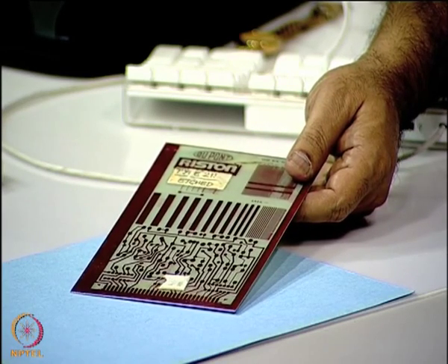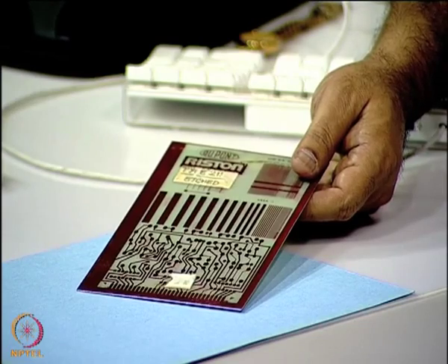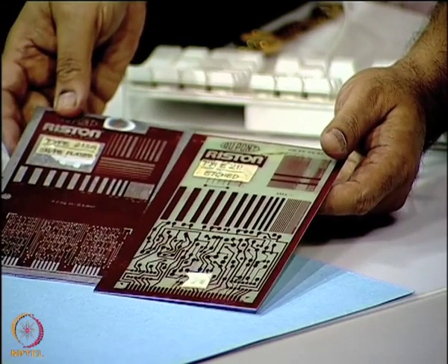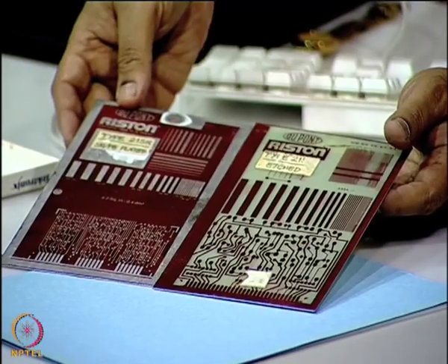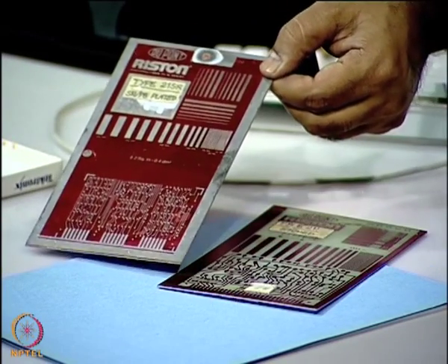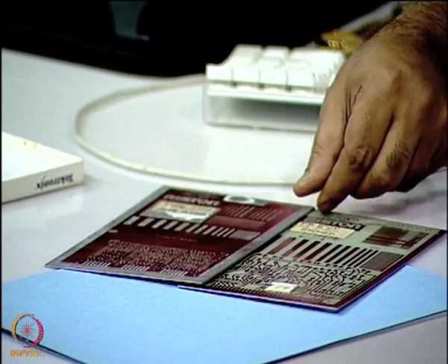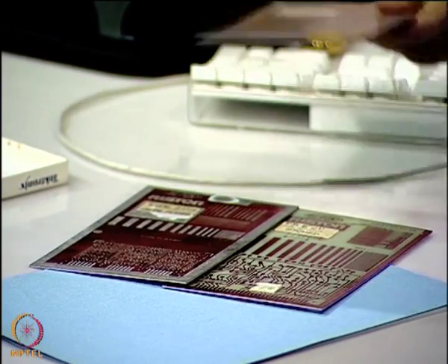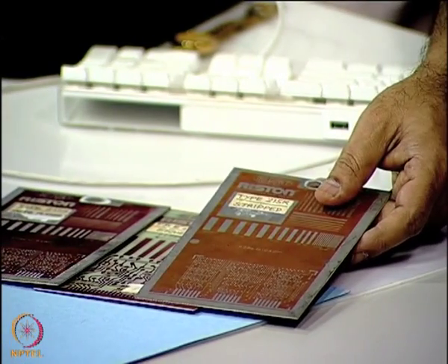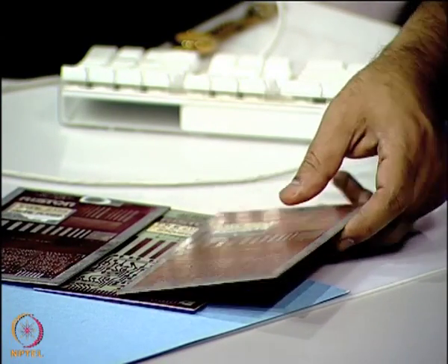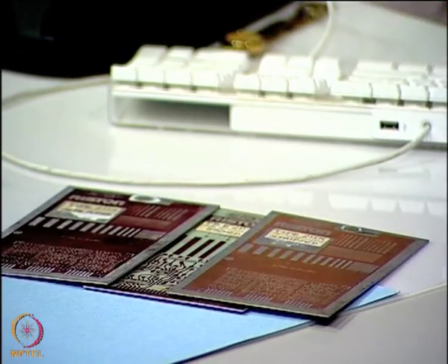process is over, this has been imaged, and then you can see alongside samples where you have specifically plated on the circuit areas, and finally the material is etched and then you get a complete printed wiring board. So, these samples will take you through the various process steps of the printed wiring board. Today we are going to focus on the complete plated through hole sequence through videos and slides.